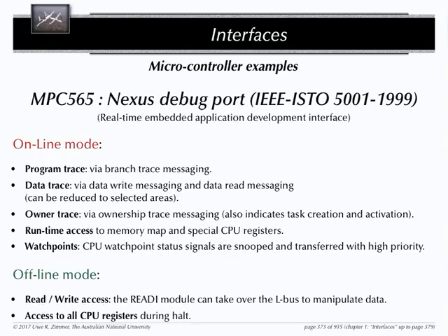And this controller then pumps this information towards your analysis, your monitoring station, and you get traces which memory cells are being used, how they're being used, how the register values change, which gives you a beautiful possibility also to analyze the whole real-time behavior of your system, because you see live on the machine how tasks are entering and leaving the CPU. You see your schedule, your actual physical schedule, live while your machine is running. You cannot do this in any other way.